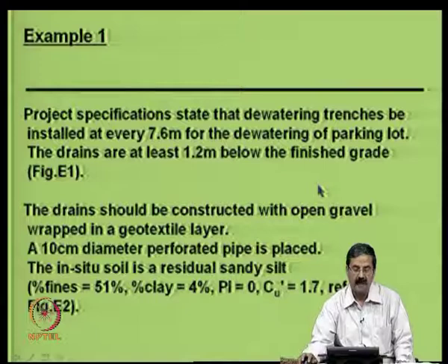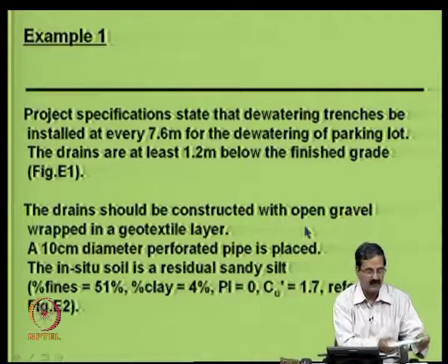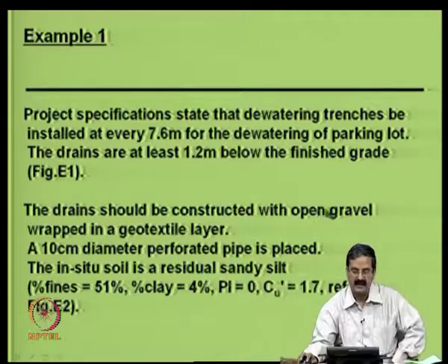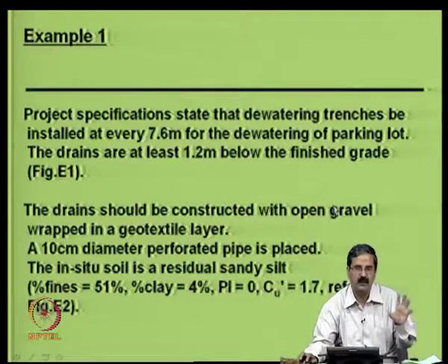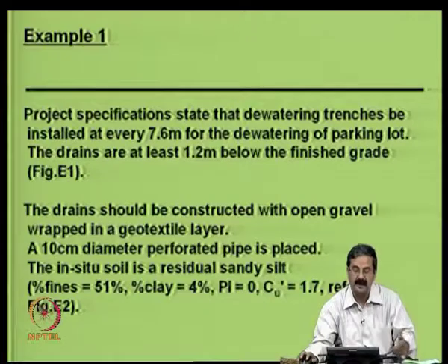You also have some properties. Obviously we want a geotextile layer here, and whatever open gravel we have should be wrapped around in a geotextile. That is because the gravel works as a drainage medium, and you do not want the clay and other materials to contaminate the gravel.